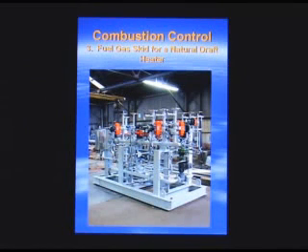On brand new heaters that have any type of an internal refractory, they have to go through a refractory cure out, which is critical. Otherwise, if you start it up too fast, the remaining water inside the refractory will start to spall, or the water vapor cannot expand fast enough to get out of the refractory block, and it will crack. So that's one reason why the cure time is critical, and that typically applies to the convection sections, which have a castable refractory.